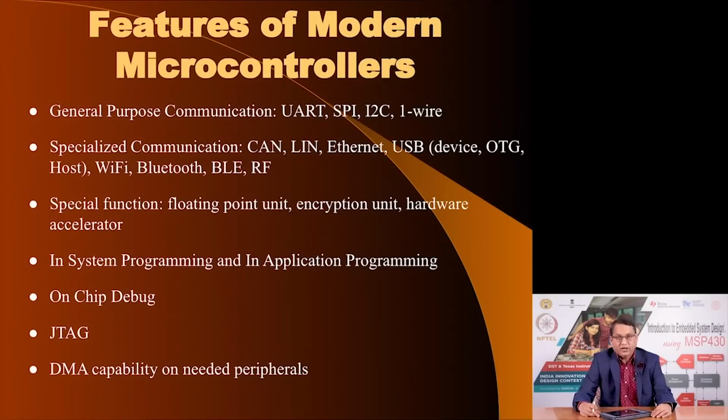Modern microcontrollers may need to communicate with the outside world in your application, and so they offer general purpose communication protocols such as UART, SPI, serial peripheral interface, I2C, which is inter-IC communication, and something called a one-wire protocol. Some of them may also offer specialized communication protocols such as CAN, controller area network, LIN, Ethernet, USB, and if it is USB, you have to find out what type of USB